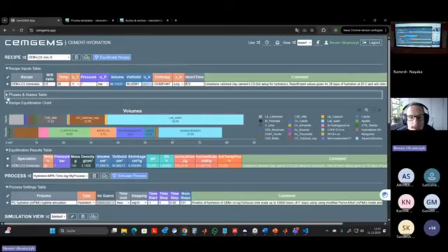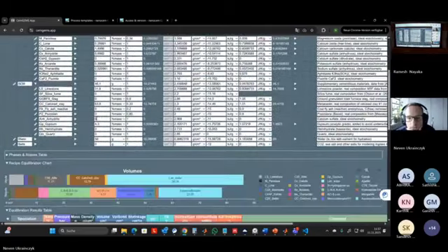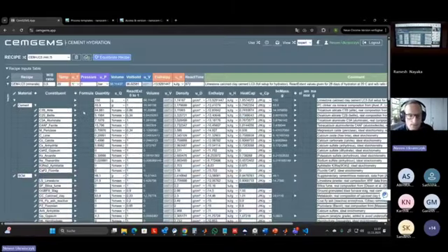You have the gamma C2S, and this one is actually not so reactive. That's why they don't use it actually. You should activate the steel slag first with, I don't know, you can carbonate or you can even add chemicals. Steel slag is not reactive actually for using in cement.